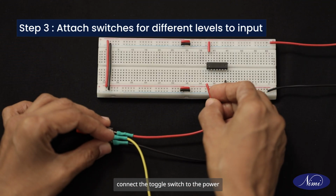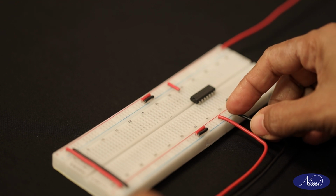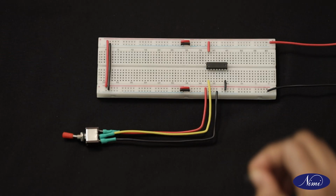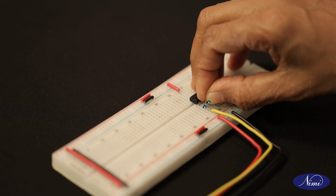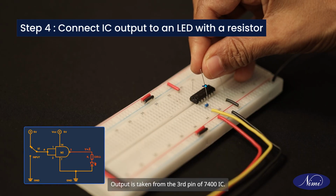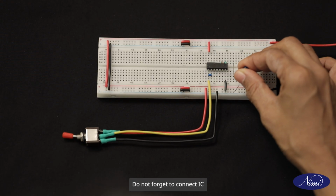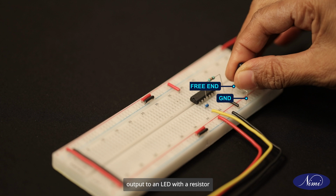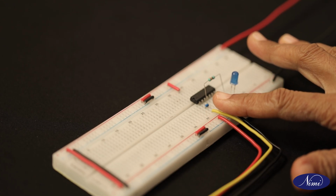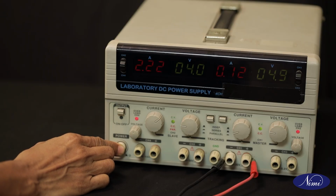Moving on to the inputs, connect the toggle switch to the power source and ground. And connect switch S1 to the first and second pin as input A. Output is taken from the third pin of 7400 IC. Do not forget to connect IC output to an LED with a resistor. With everything checked, switch on the 5V DC supply.